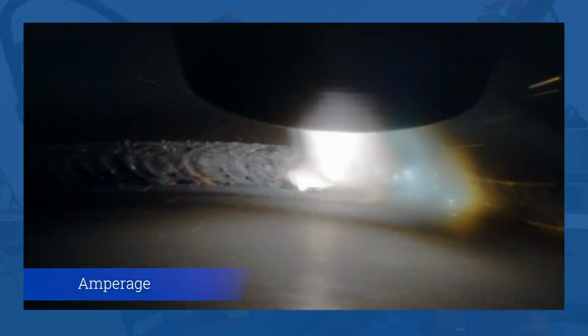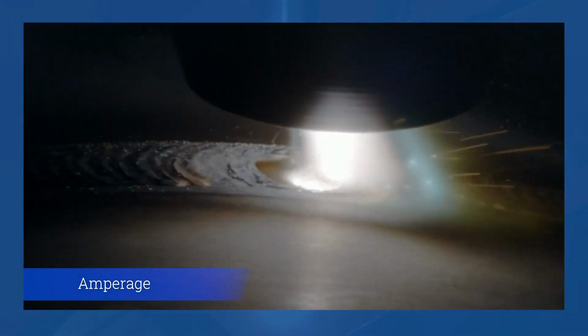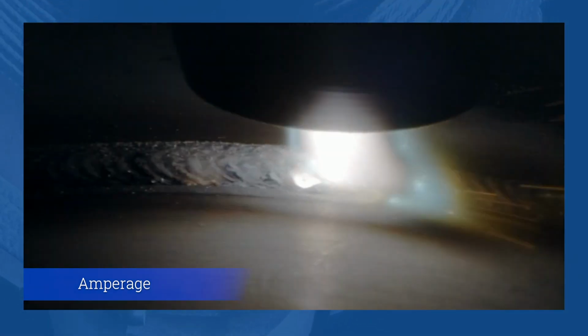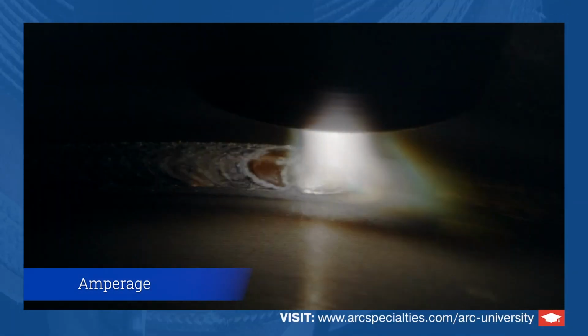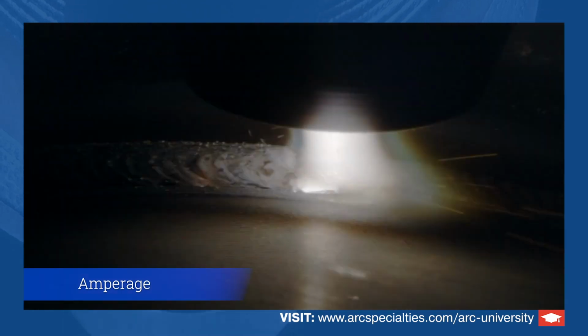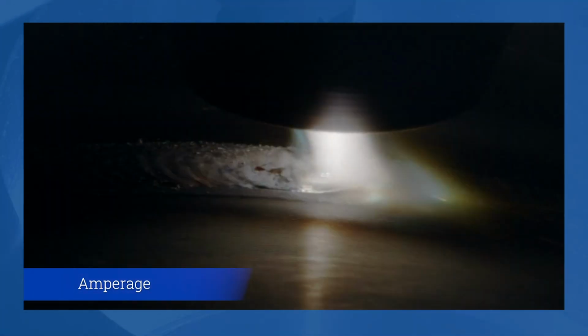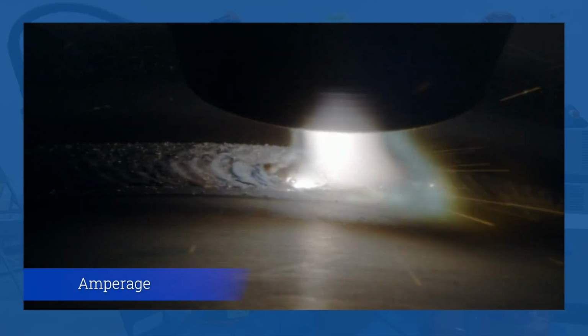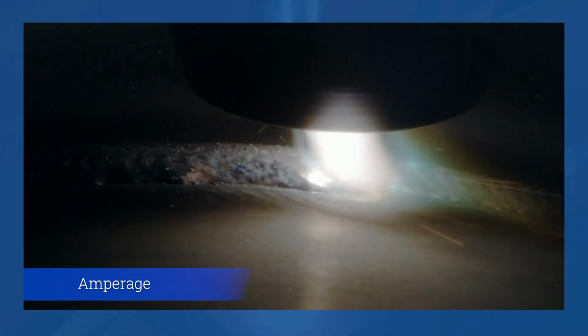So let's start off with amperage or current. This is the variable that really controls heat input more than anything else. Right here, we're running at 100 amps. You can see a ripple with each pulse behind it. And we're going to now turn up to 120 amps. That's not a great deal more, but what you can see in the back of the puddle is we've lost the ripples with each pulse. But more importantly, you would see increased dilution in your part and diminished hardness.